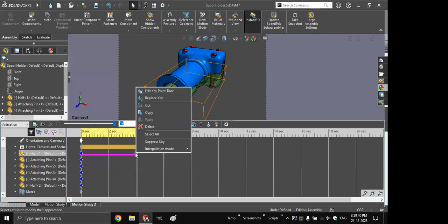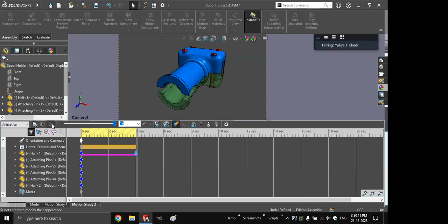Right now, if I right click on this, I'll find this interpolation mode, which I said before is the transition between one type to another. And the default is linear. So let's say in 1 second, it changes from 0 to 100%. So after half a second, it changes to 50%. After 0.75 seconds, it starts changing 75%, and so on. But I can actually change it. So snap, for example, it stays the same all until the very last second. So if I change it to snap, it doesn't do anything at all. And at the very last moment, it changes right away.